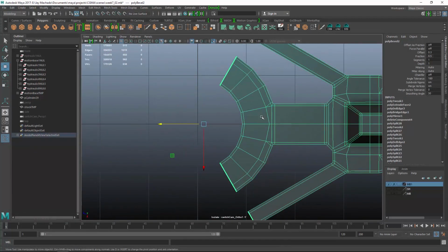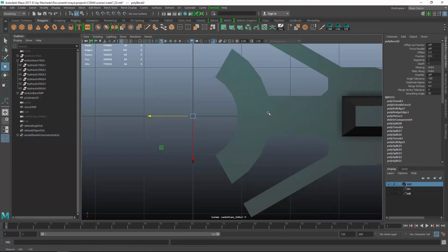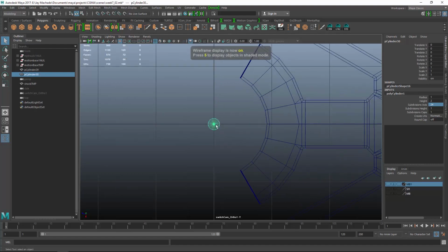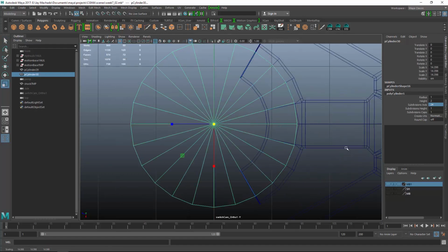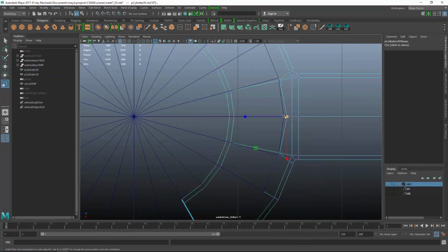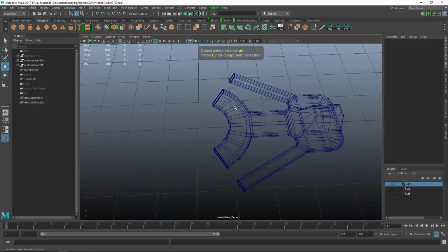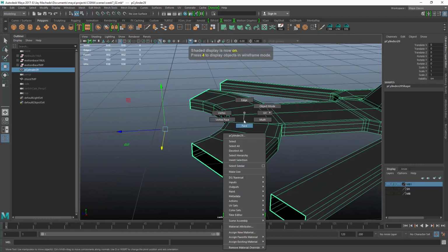Well, so that's cool. I think I want to do something similar with inside of this ring as well. I'll give some thickness to that. So now I'm just going to create another 24-sided cylinder. And you can see that we've lost some of the curvature when we did the bevel tool. So I'm just going to use my point snapping and just get some of these vertices back in the right spot. Go ahead and delete that cylinder because it was just a guide.